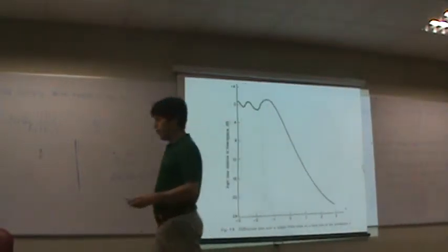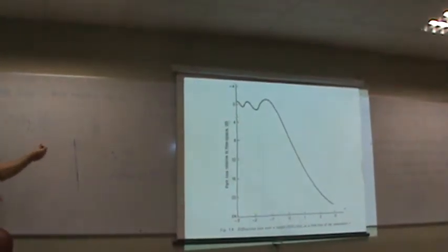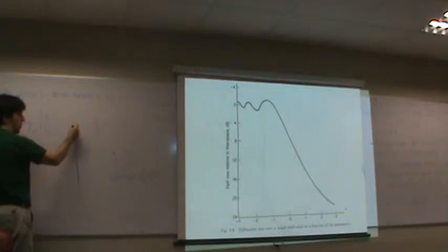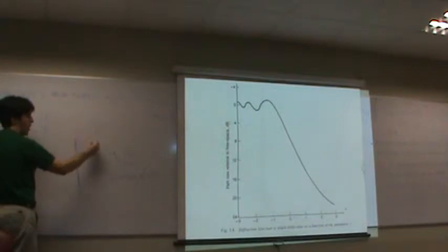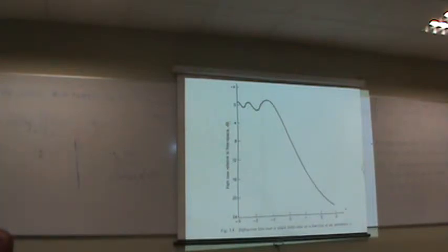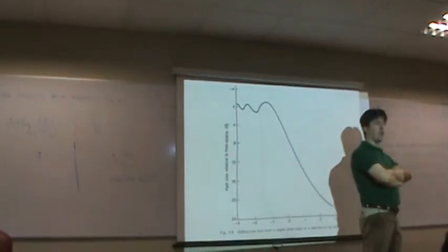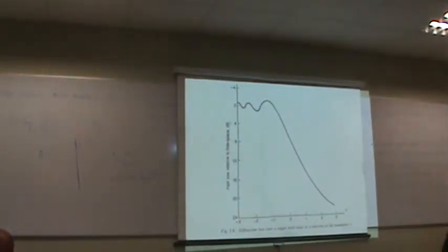Again, what is happening is that who is contributing to the receiving field? All the unblocked Huygens sources that are radiating somehow some energy towards the receiver. And we will use this graphic or the equation that I'm going to give you to design the radio links when we have some obstacles. One obstacle in particular. Multiple obstacles is more complicated.